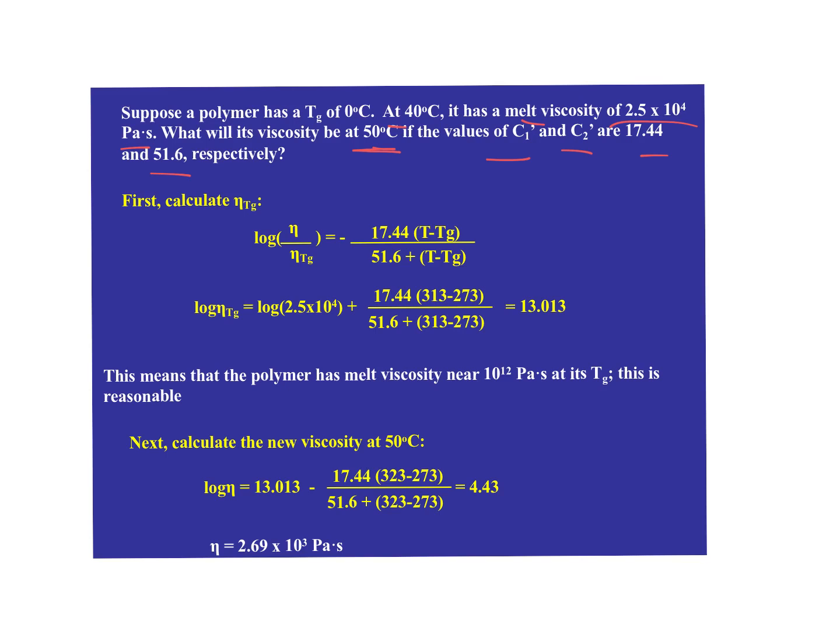Anyway, so if we calculate first off the viscosity at the value of the glass transition, we get this as our reference point based on the data that's available to us using these equations. And so we know that the log of eta at whatever condition is equal to the log of the ratio of eta to eta Tg, which is equal to this overall expression, and we need to rearrange things. This is where you guys need to go back and brush up on how to work with logs. You can take this ratio, break it up into two separate values, one minus the other, and then move it over to the other side of the equation.